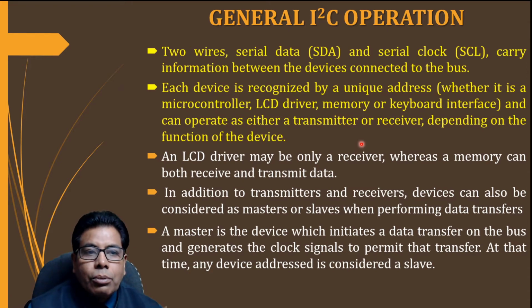Whether it is a microcontroller, LCD driver, memory, keyboard interface or ADC, each will have a unique address and can work as a transmitter or receiver depending on its function. For example, the LCD driver will always be a receiver because it's an output device, whereas memory can work as transmitter or receiver. And of course the microcontroller, which is a master, can work as transmitter or receiver.